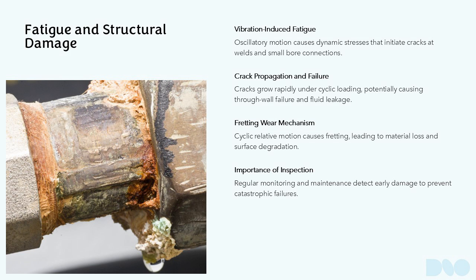In addition to fatigue, vibration can cause fretting, a wear mechanism that occurs when two surfaces in contact experience cyclic relative motion. Fretting leads to material loss, surface degradation, and potential loss of containment. These issues underscore the importance of proactive inspection, monitoring, and maintenance strategies to detect early signs of damage and implement corrective actions before failures occur.